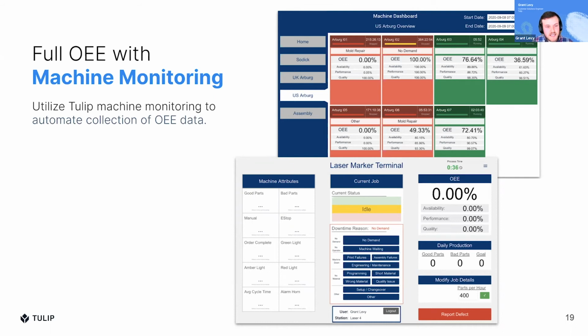If they speak OPC UA, we can take these machine tags in and make decisions based on tag values. You might have a machine with a Boolean tag that says running, yes, no, good part, yes, no, or bad part, yes, no.